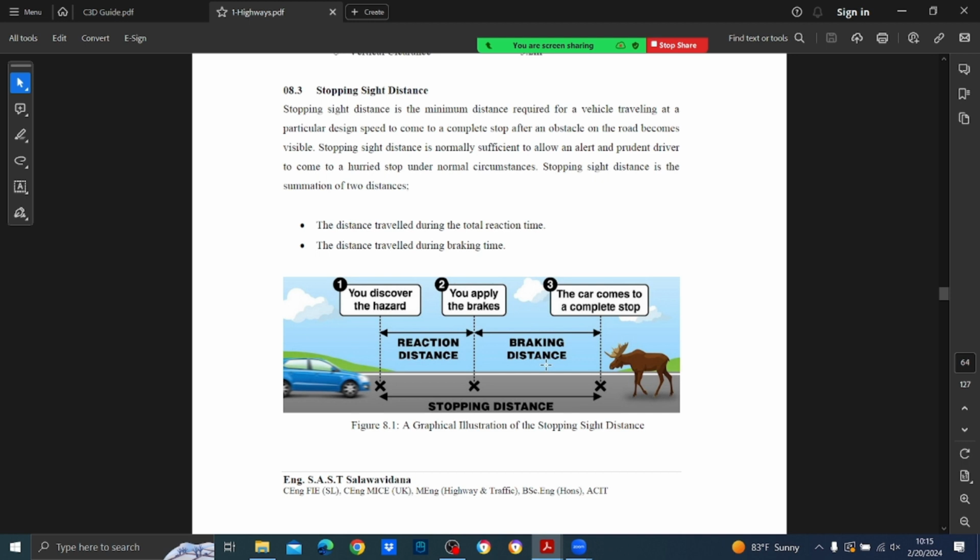Some people, when they are practicing, see there's something there, they think apply brake, and then what happens is they press the accelerator to the bottom. But anyway, just to understand that I have to press the brake pedal, not the accelerator, that also takes some time. That is why there's a reaction time. Usually we take it as 2.5 seconds.